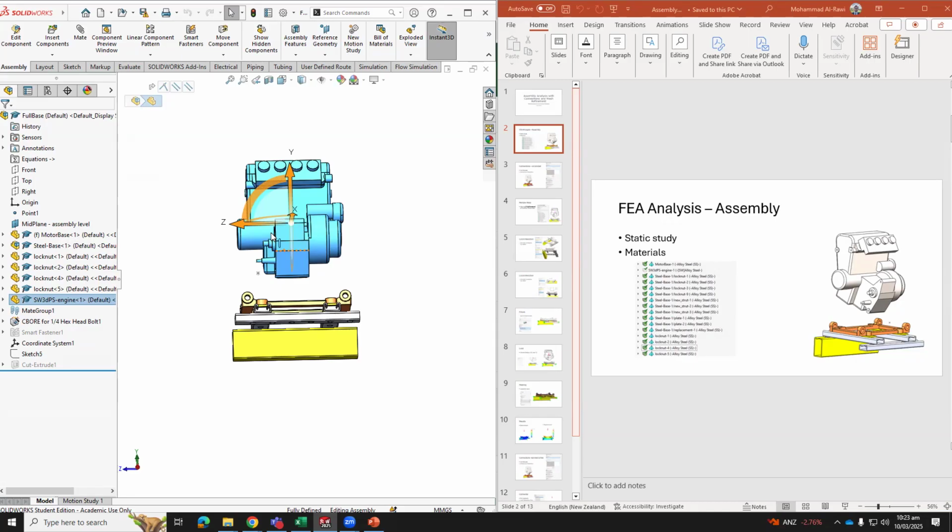So first of all, the materials are all specified for me, for simplification of this example, to be alloy steel. And I'll show you the process to take that engine and convert it to a mass, to exclude it from the simulation, because it would take time for finite element analysis such as meshing. And then we set the basic contact, and then we compare the results and see how we can improve that contact to understand what it looks like in assemblies.